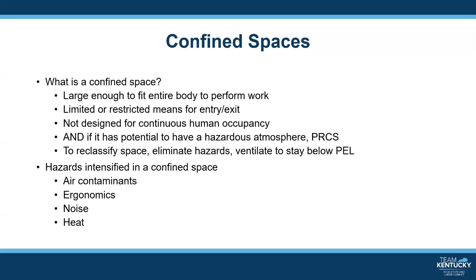Although the confinement and spatial enclosure of the environment, natural ventilation in most cases is insufficient. Most of all, an oxygen content between 19.5% and 23.5% must be maintained while the employee is inside.